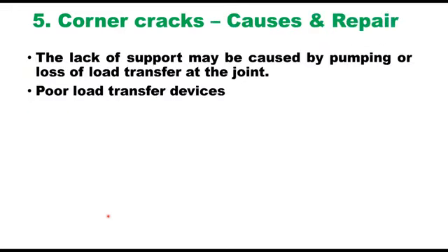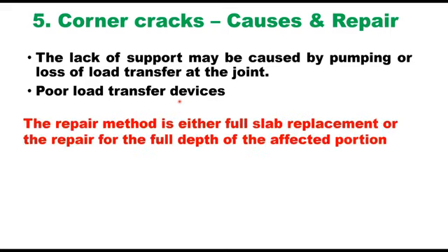Corner cracks are caused by lack of support due to pumping or loss of load transfer at the joint, or it may be because of poor load transfer devices. Load repetition combined with loss of support and curling stresses usually causes cracks at the slab corner. The repair is either full slab replacement or the repair for the full depth of the affected portion.